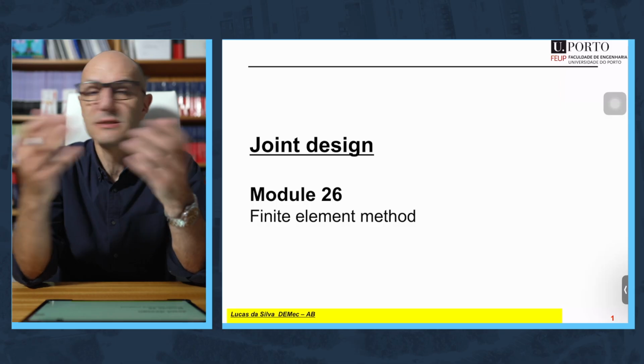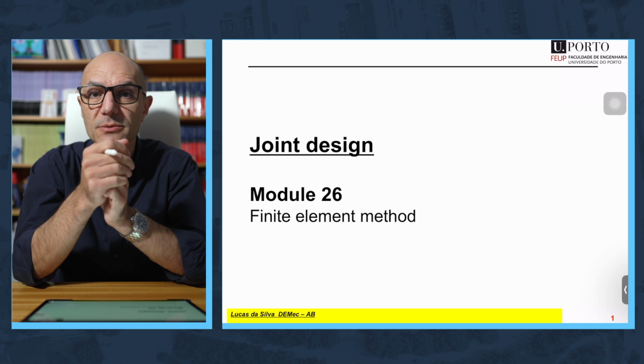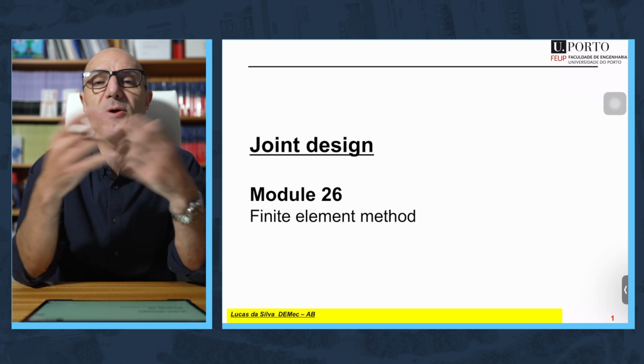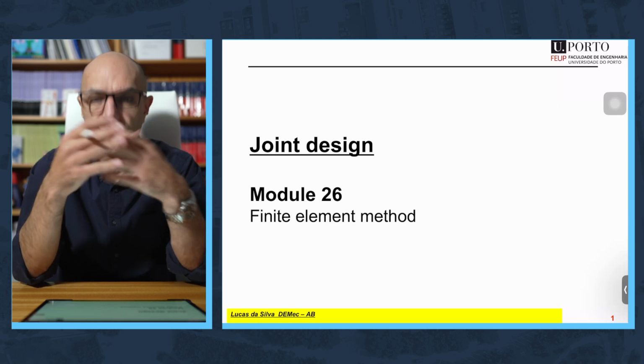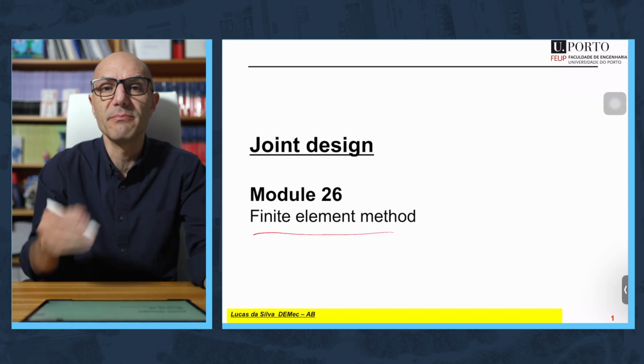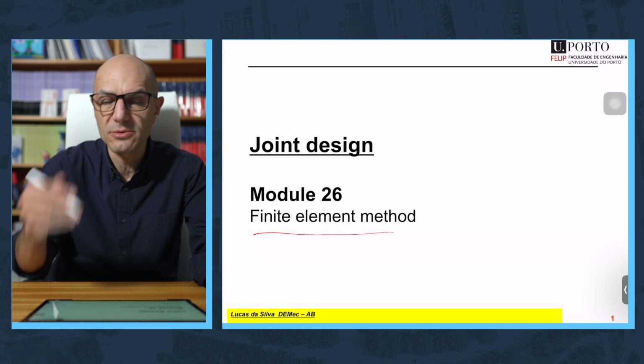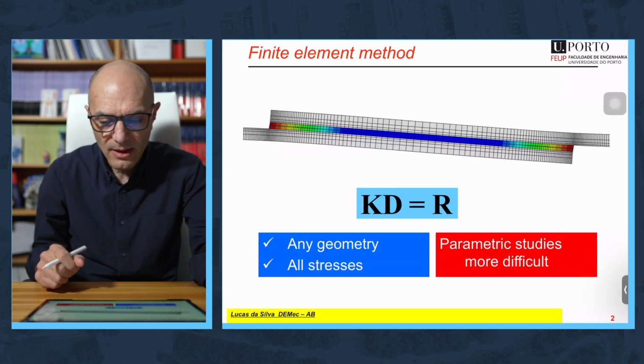In practice, in many cases, for complex joints or for complex constitutive models of the adhesive or the adherends, the differential equations that are generated become too numerous. There are too many, and there is no direct mathematical solution. In that case, you need an approximate method, and the most common method used is the finite element method. So it's used a lot in the context of adhesive joints.